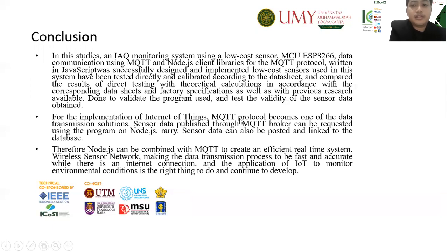And then this is the conclusion of our research. In these studies, an IAQ monitoring system using a low-cost sensor, MCU ESP8266, and data communication using MQTT and Node.js, client libraries for the MQTT protocol written in JavaScript, was successfully designed and implemented.